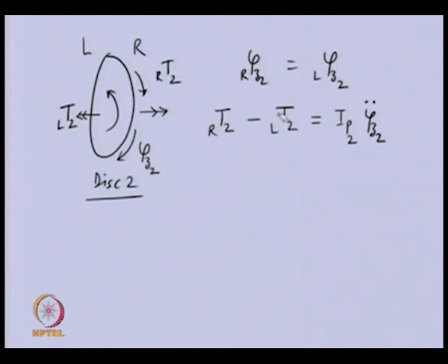Now, we are considering free vibration or forced vibration. If we are considering free vibration, we expect that whatever motion takes place will be simple harmonic motion, with the natural frequency, because if we disturb the system, we expect it to oscillate with the natural frequency of the system.